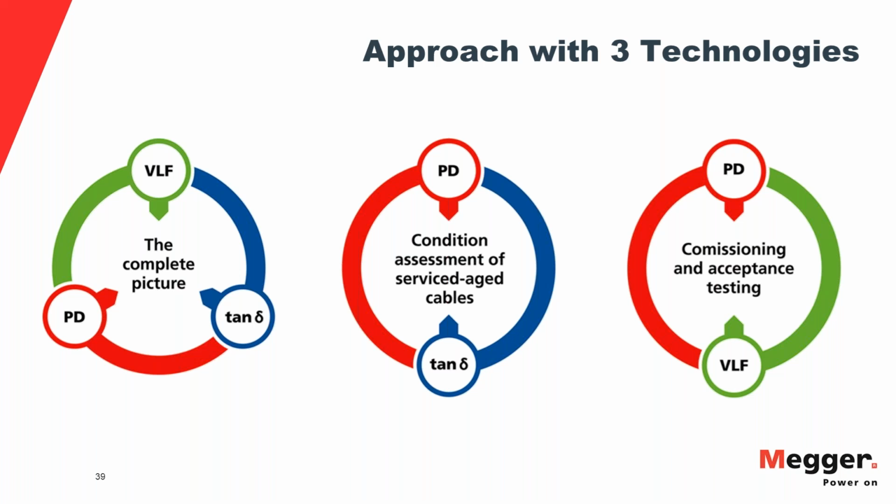The other thing is, when we say the cable rating in the power industry, it is always a 3-phase rating, okay? So when you say 15 kV class cable, that means the individual cable, when you have 3 of those, does not see 15 kV. That 15 kV is phase to phase between 2 center conductors. You would be able to measure that. The cable insulation itself sees U0, the phase to ground, the line to ground value.